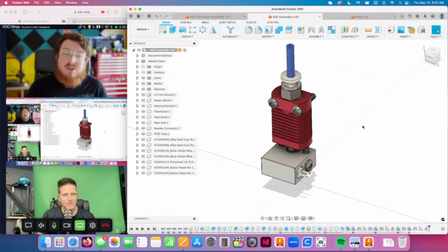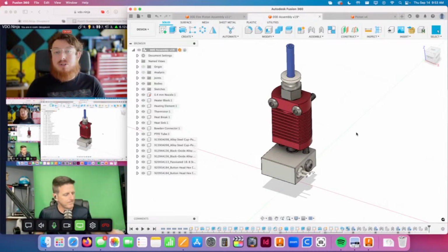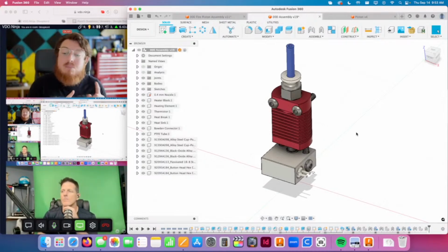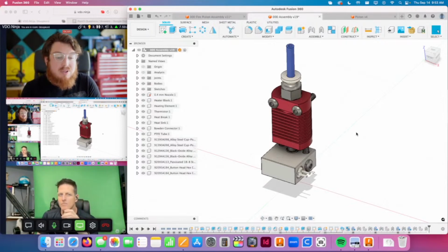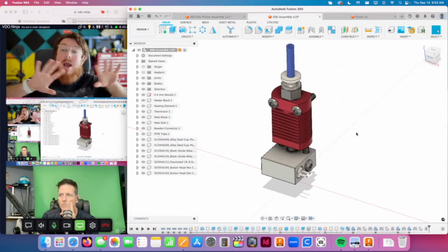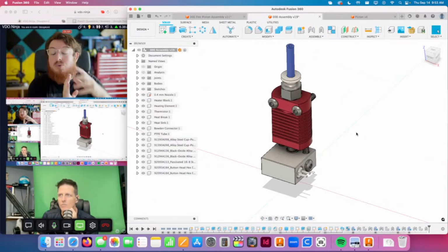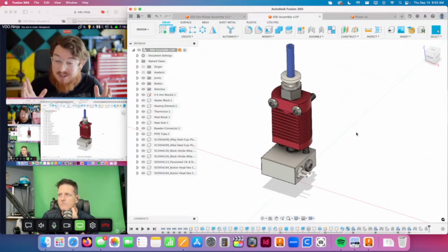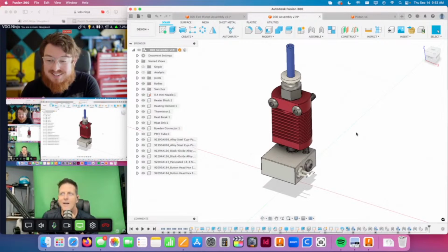Yeah. So the move command is a little funky, especially in assemblies, because you can select exactly where that move location is, but it really depends on your project. That pulls into a little bit more of the CAD philosophy, where you need to build up a skill set to know exactly where you model things, on what plane, in what orientation, so that it will help you later down the project. If you know that the project you're making is symmetric, then you need to pick which plane makes the most sense and which orientation makes the most sense. Okay. So again, a little planning can go a long way here.